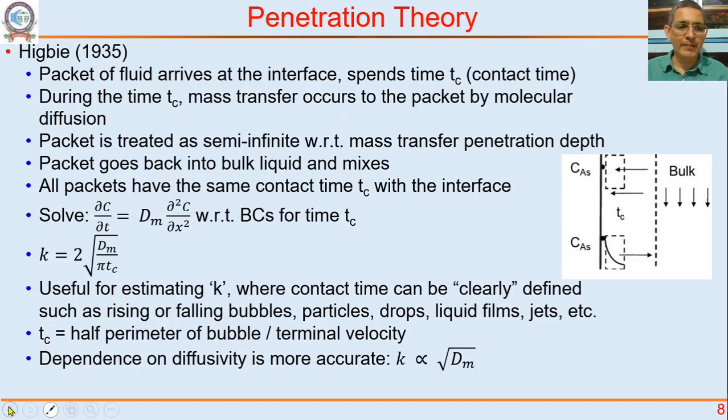So if a bubble is rising, let me just help you to visualize. So imagine this is a bubble. This bubble is rising. It is as if the flow of the liquid relative to the bubble is like this. So if an eddy comes and sits here, let's say, let me draw another color. Let's say liquid is flowing down, there is an eddy that comes here, and then that eddy slides from here to here. So what will be the contact time? It will be the time required for that eddy to go around the bubble. How will you get that? This distance divided by the rise velocity of the bubble.